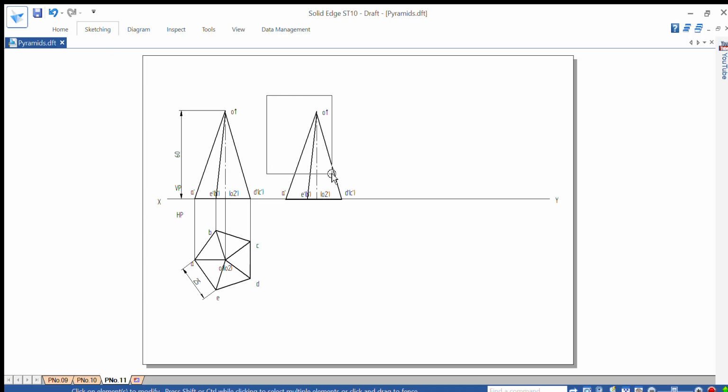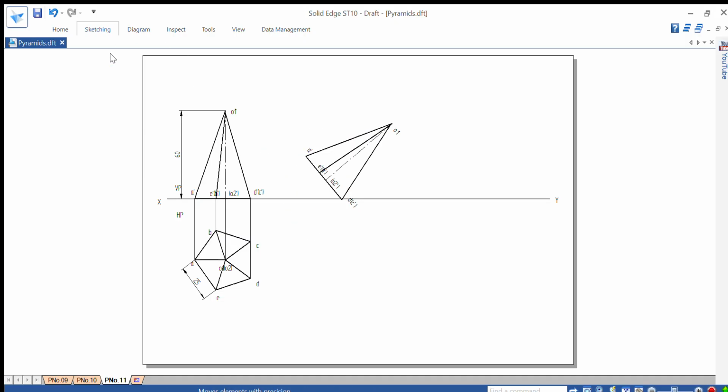Through window you select center of rotation is D dash, point to rotate A dash, 90 minus given angle. In the problem we have given 40, then the angle you have to give is 50. Click it and move those text upwards with the D dash, and switch off the copy. The D dash and C dash have to be moved upwards, and zoom this much area.